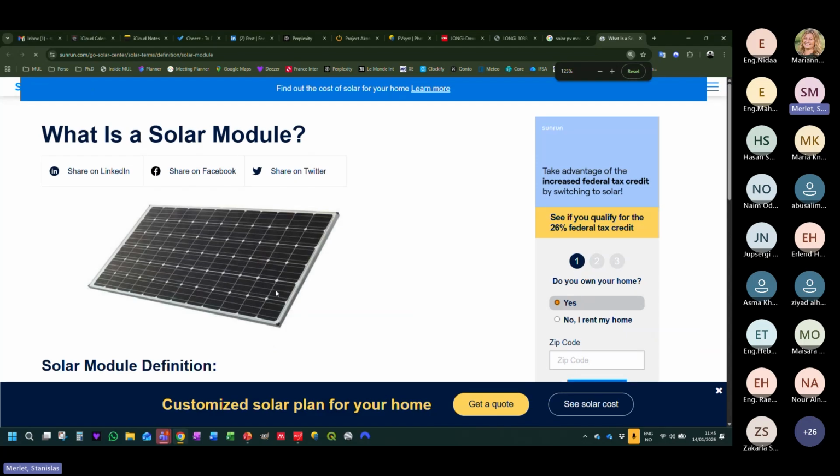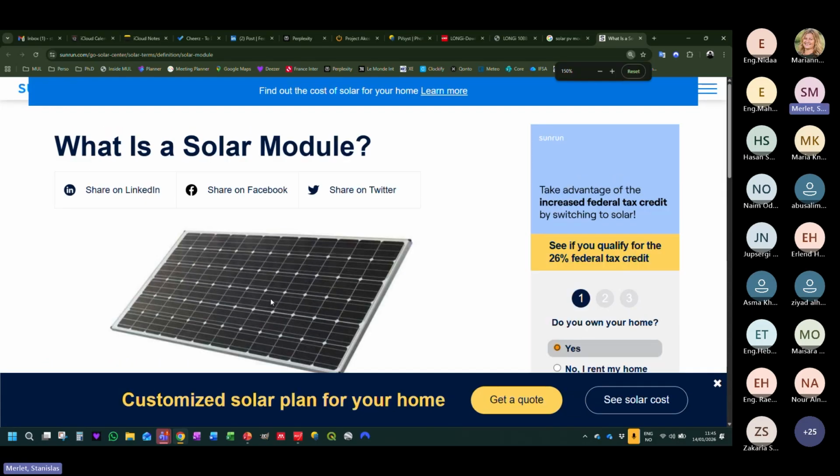Yeah. So here you have the cell, but then you need to collect the energy produced by every cell. And for that, you have a grid of metal, because it can be different materials, but you have a grid of different metals on the cells or on the backside of the cells. I mean, there are a lot of different technologies for that. And what you can see in there, the lines in there, that's what we call the bus bars. So that's the biggest part of the grid that is integrated in the cell to collect the current